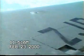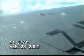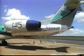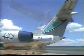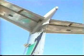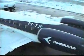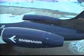However, thickened fluids may dry out during flight, and residues may form in aerodynamically quiet areas. The residues may turn to a gel, which can freeze in flight, potentially restricting the movement of flight controls. Such an occurrence has never been reported on an Embraer regional jet. However, operators are reminded to frequently inspect control surfaces, gaps, and tab hinges for signs of residual gel. If an approved fluid shows to be subject to gelling, poor water wash-off, or unusual dry-out, Embraer should receive a report of the occurrence.